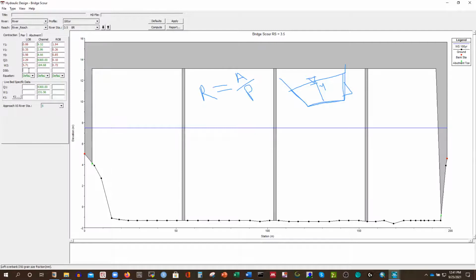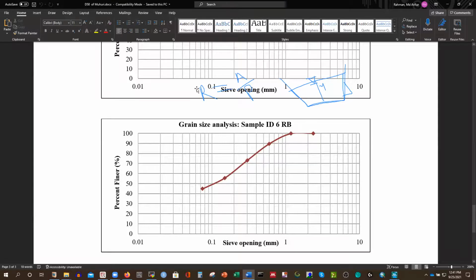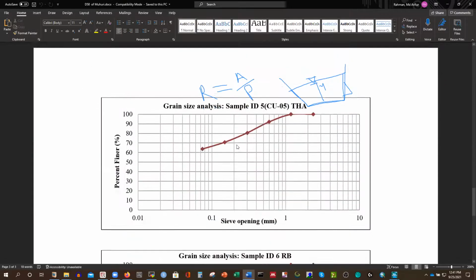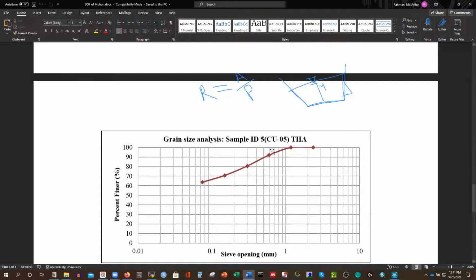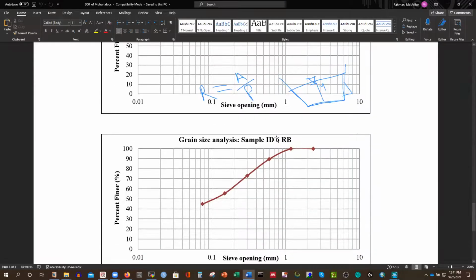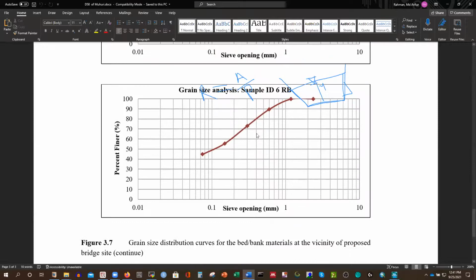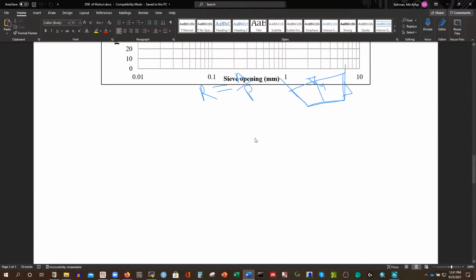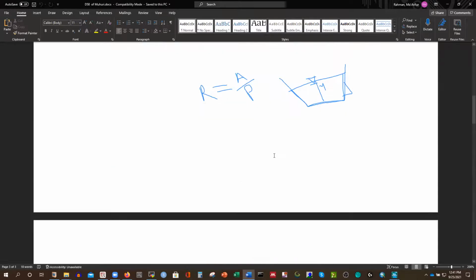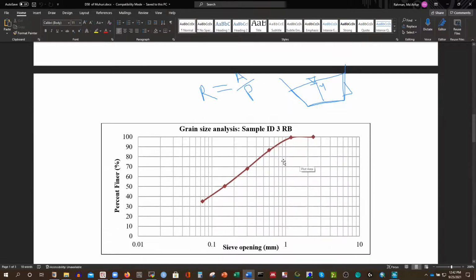And then the D50 from that CV analysis we have here, right? For the bridge section, from the bridge section you can select. So we have that upstream of bridge section number 5. That is the approach section. That's why we have the value there, and we also have the distribution for the bridge, right? So that is the bridge section BR. And if you want to calculate the D50, how to read that graph, just follow D50, right? And here, and it will be like there. So this is 0.1, 0.2, so that will be 0.15, okay? 0.15, so put it there.